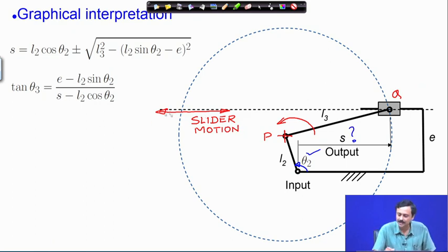So, the slider can exist or move on this line. If you want to assemble the mechanism with the hinge Q, with this link PQ and the slider, then it is the intersection of this circle with this line of motion. As you can see, there are two intersections, one is what I have shown, the other is here.